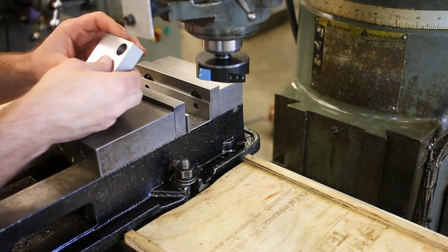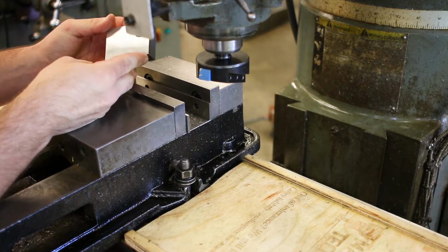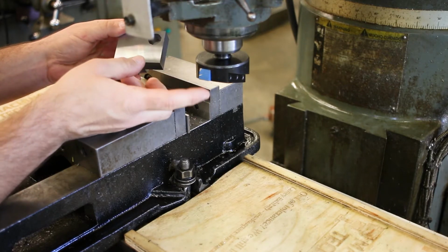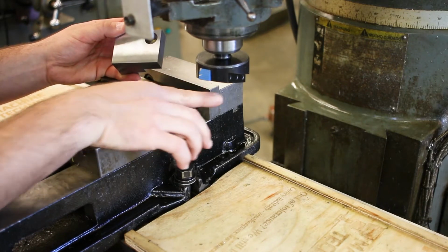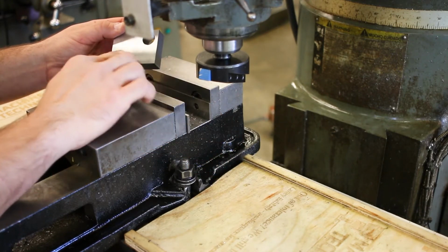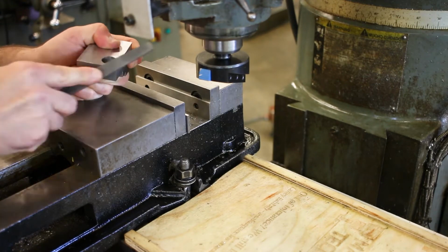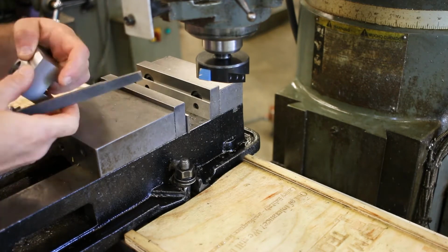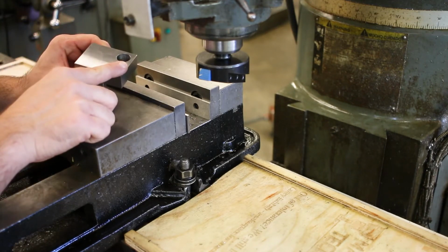All right. Go ahead and take that out. That looks really, really nice. Okay? If your surface doesn't look good, then it's probably because your cutter is dull and you really need to sharpen this. I mean, if this cutting edge is dull at all, it's going to leave a really crappy finish. Okay, Datum feature A is finished.